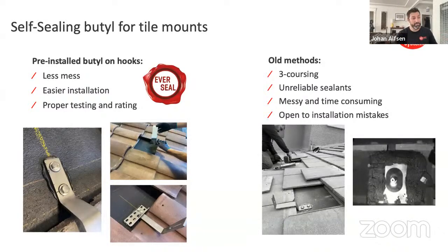As a retrofit, it's very messy, it's very time consuming, and you have to bring big buckets of tar up there. Some installers have it down to a science and an art, and they do it. And like I mentioned before, some just rely on sealant and just putting in sealant all around the hooks, which you can see at the bottom middle picture there in black and white. So we've been introducing the EverSeal technology, which is our butyl asphalt compatible seal pad. And it's self-sealing, meaning that it seals itself once you install it, and you don't have to use any sealant at all. So this is much cleaner, much faster, and it's all pre-built in there.